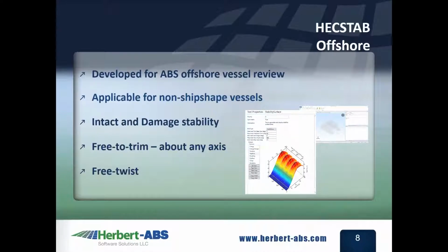in this case, we're actually looking at free to trim. We can look at stability along any axis. And a lot of times when you're looking at offshore vessels, you're looking at stability a full 360 degrees around the vessel. So we provide tools for simplifying and standardizing that type of calculation and approach. We also have the newest methodology for evaluating offshore stability, which would be the free twist approach, where it's actually looking at the path of least resistance and allowing the vessel to actually freely rotate as it's being heeled over.